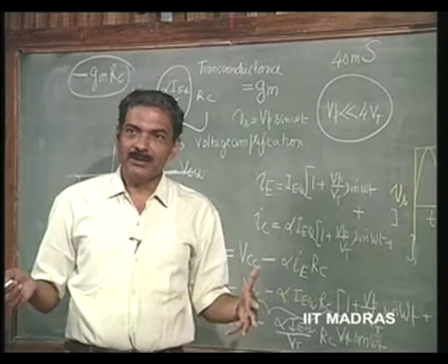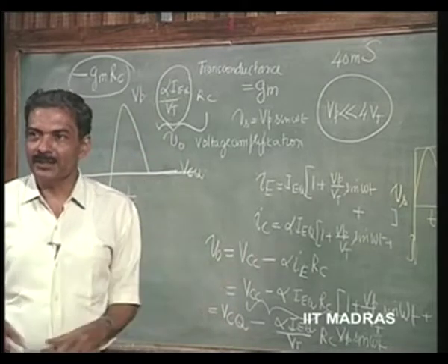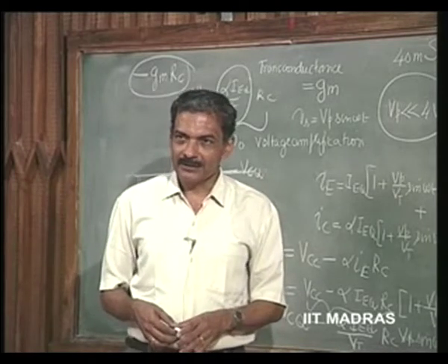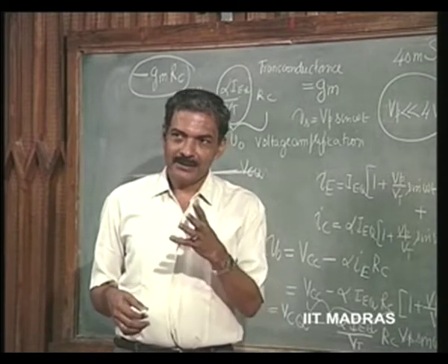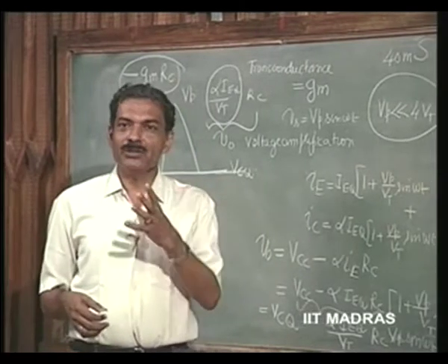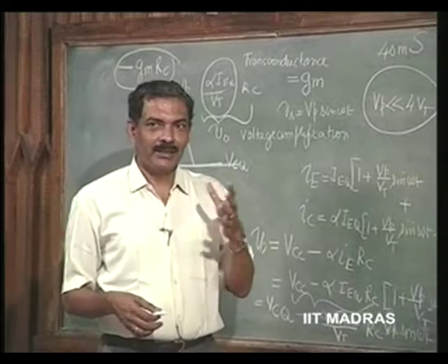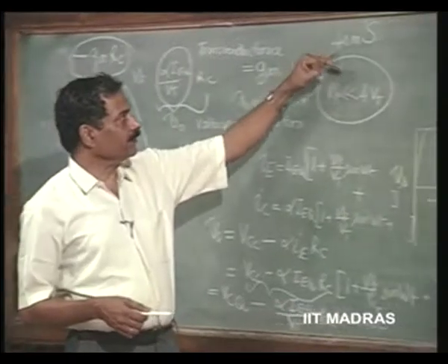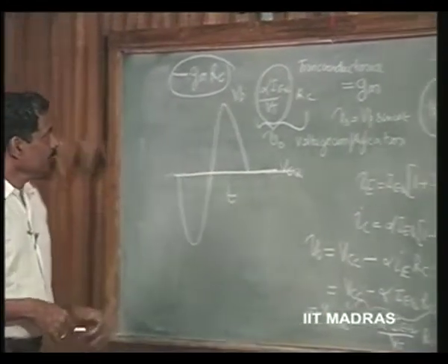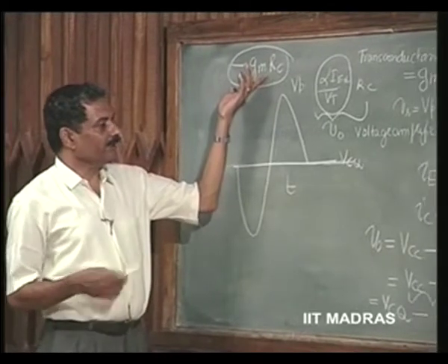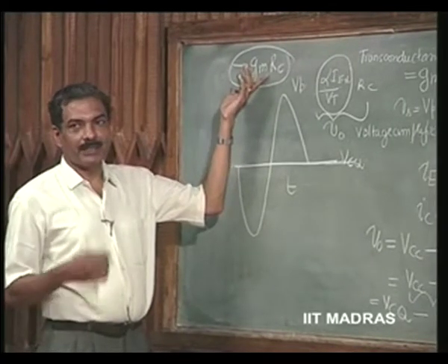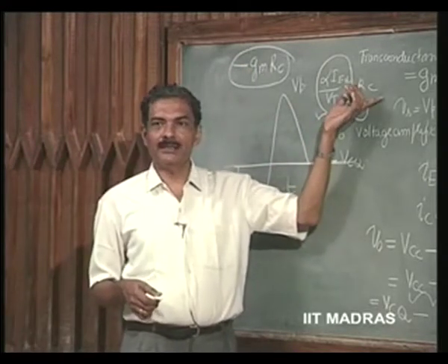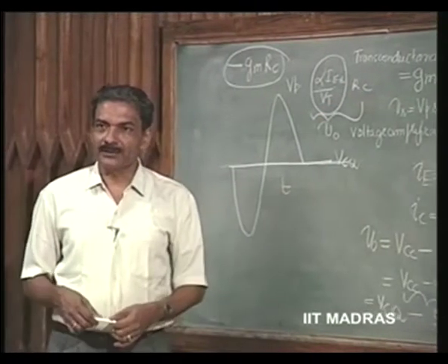So, if you just know what the operating current is, you know the transconductance of your bipolar junction transistor. That is not the case with other active devices. The greatest advantage of the bipolar junction transistor is you know most of its story the moment you know the operating point. So, this is an important factor that you should remember, that the transconductance is immediately known the moment we know the operating current. And if you fix the collector resistance RC, then the amplification factor is also known.